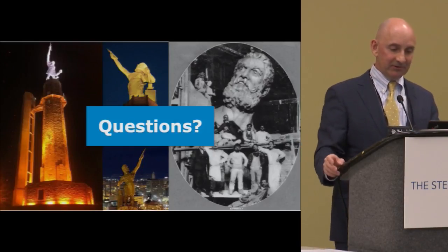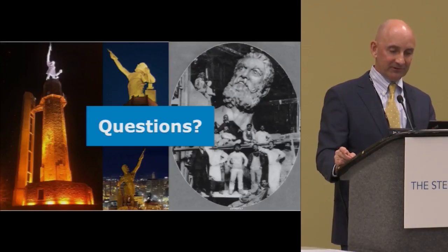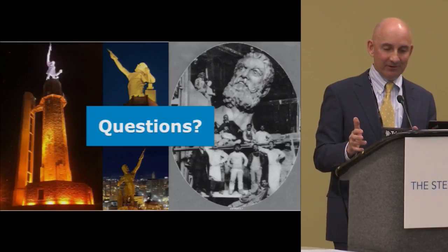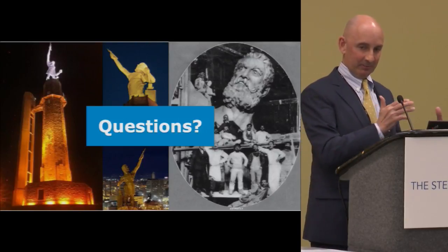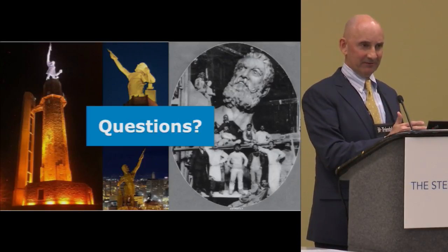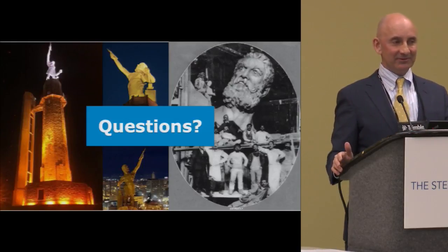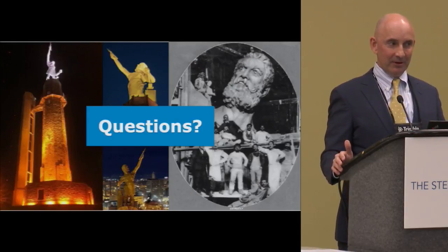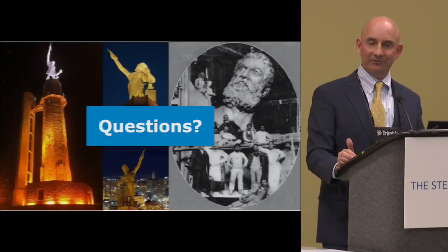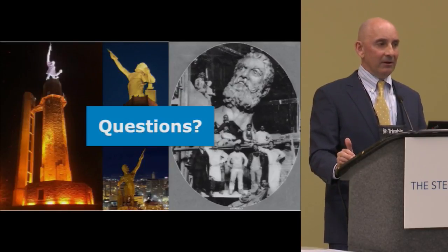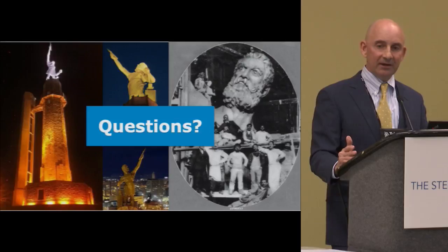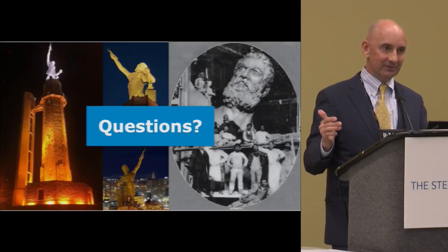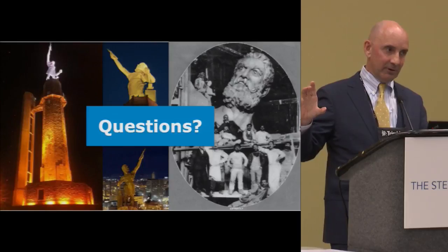Yeah, that's right. And there is a difference. The question was why this interaction is not the same as what was published in a paper. I believe you're referring to the plastic strength of rectangular connection elements paper. There's a paper in the Engineering Journal that was published sometime in the last 3 years or so, titled Plastic Strength of Rectangular Connection Elements. And in this case, for the rectangular connection elements, it would only apply to the double coped.